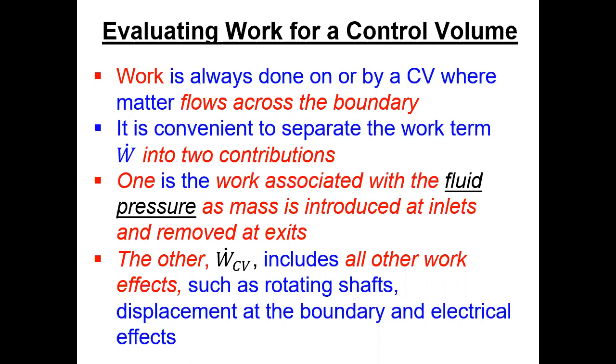Now this is new for us, okay? So if you've got matter flowing in or flowing out, there is work associated with that flowing fluid material, okay? It is convenient to separate the work term, which is W dot, into 2 contributions. So we're gonna split this work term into a couple of different pieces here. One is the work associated with the fluid pressure as mass is introduced at inlets and removed at exits. And we're going to call this flow work, okay?